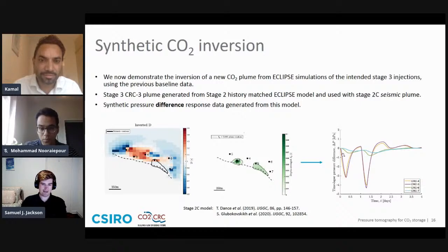And the generation of that pressure response is different, and you can actually pull out more, or I should say different information from the field. So the combinations of different injection modalities can then really inform different frequencies and different spatial length scales in the domain. So you might do a very short injection or a very long injection when you're trying to uncover information about the different length scales of heterogeneity, at least from the aquifer characterization.